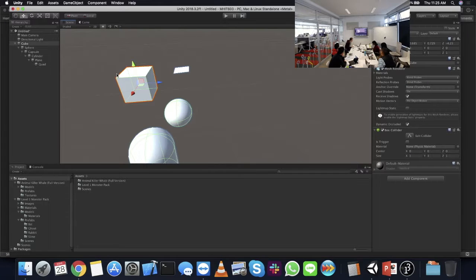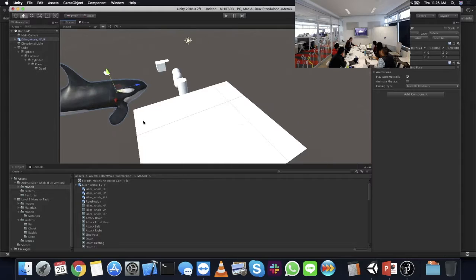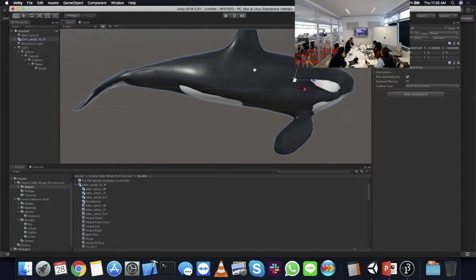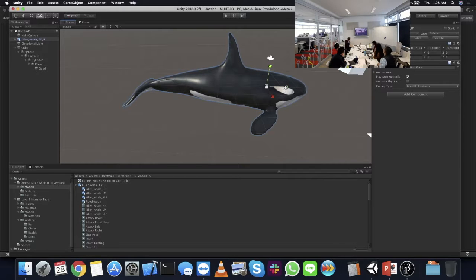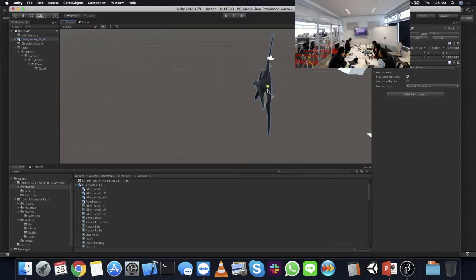But the same thing is true in Unity. So if I grab something, actually no, where's that whale gone? So here's my whale here. And if I shrink him using the shrinking tool, he's facing towards our right. If I grab that one and shrink him, you notice it's getting smaller and smaller, and you can see in the scale his Z value is getting smaller. It started at 1, and it gets smaller and smaller until we eventually reach 0, where he's collapsed on top of himself, almost.